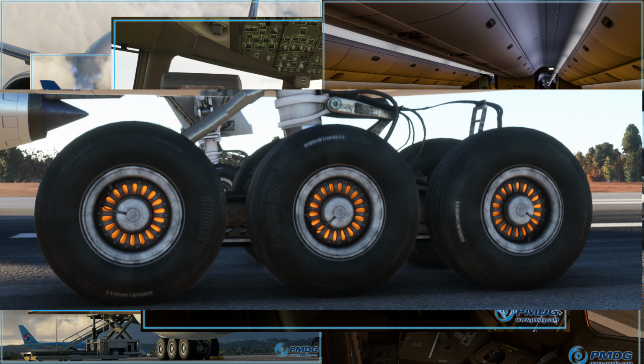The brake system of the 777 is designed to reject the takeoff close to V1 that can easily be 170 knots in this airplane at 350 tons at the maximum takeoff weight. So obviously the brakes have a huge amount of power available to them. But during normal taxi, far less braking power is required.